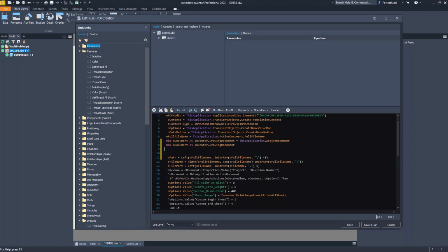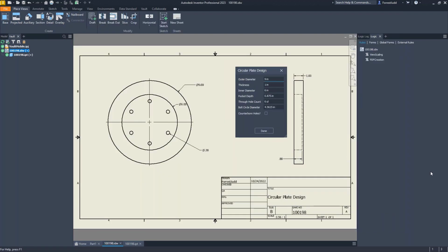And here's a thank you for those of you that replied as well. We've got some folks in here that, when they transitioned to 2022 Inventor, did have to install VBA. Pete, the person who asked the question about whether you'll have to do that when you go to 2022, yes, you'll have to install VBA. It's not a big deal, it takes a few seconds to install, but it's a step that if you don't do it, your macros aren't going to work. So thank you for those of you that replied, confirming that you had to. I appreciate that.